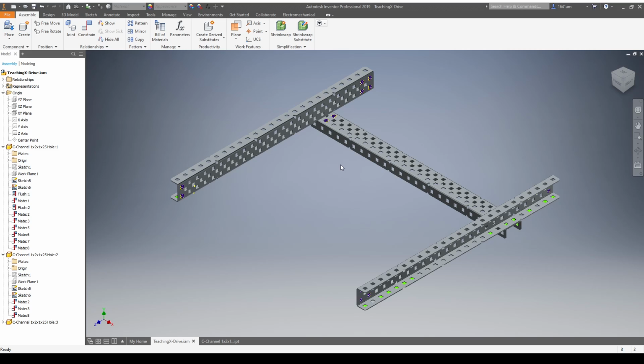Oops, I double clicked. Make sure that it gets highlighted, and then click open. Another pop-up comes over here on the left side, and that's basically because it's opening a step file. So it's converting it when it opens it from a step file to an IPT file, which is really useful because you don't have to actually do anything. So then you click OK, and it converts it.